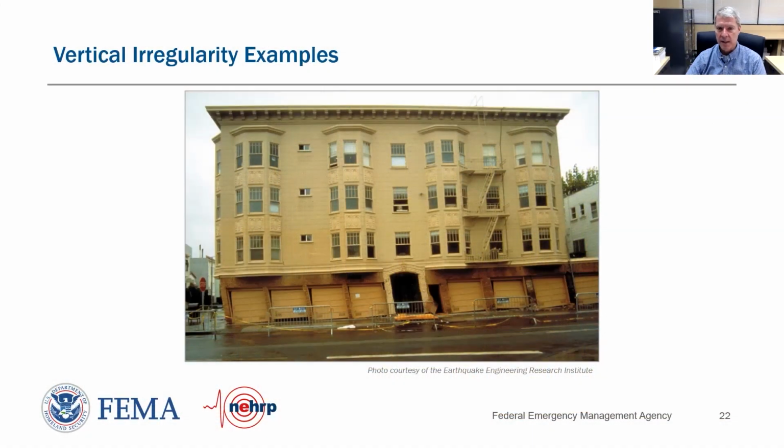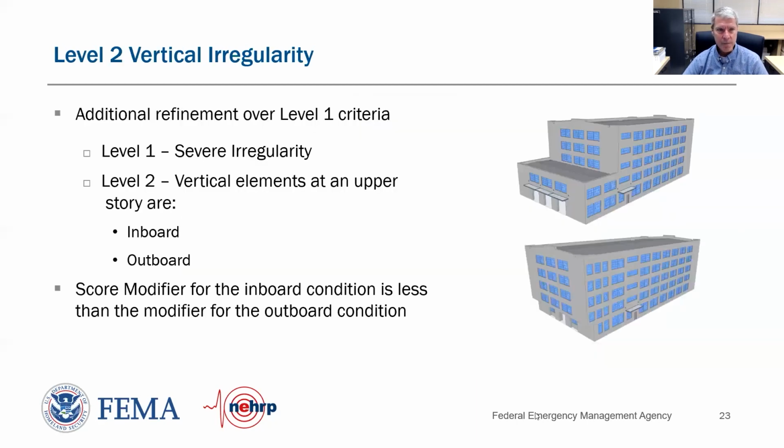And the photograph shows that the building is leaning to the left, from the foundation up to the first level above the top of the garages, maybe a foot. So it's pretty close to collapse in this regard. But that's an example of a weak or soft story where we don't have any lateral resistance in plane at the base of the structure due to the garage door openings.